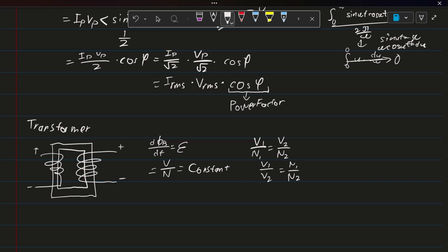Now this is a weird idea: how could you transform the voltage just by adding nothing into it? It turns out that you would need to sacrifice something else, which is going to be current. So you couldn't truly create an ideal transformer anyways. If you have, let's say, a perfect material which could contain all of the flux, you would still need the current just to transform from one energy to the other. So we're not breaking any thermodynamic laws in this case.